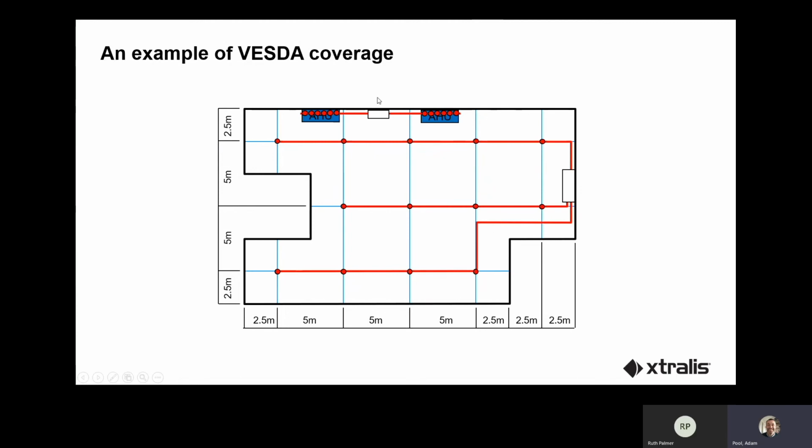But of course, within the design, we've got to consider the return air grills as a priority. If aspirating is only ever used at one point in a computer room, it's across the return air grills. Conventional detectors can be used elsewhere, but obviously there is a benefit to having high sensitivity within the facility as well, because if the air handling units fail for some reason, firstly, there is a greater chance of a fire alarm condition occurring because there's a greater risk of fire starting because there's no cooling, and we've still got high sensitivity detection protecting the space as well.